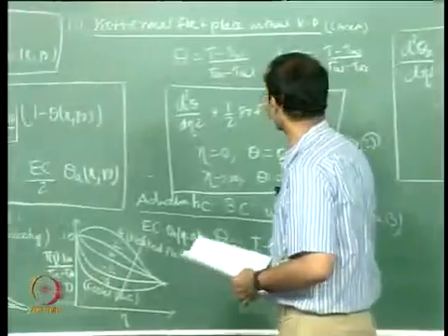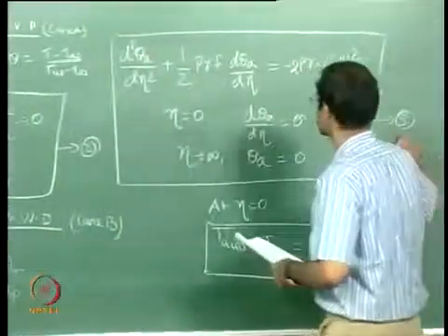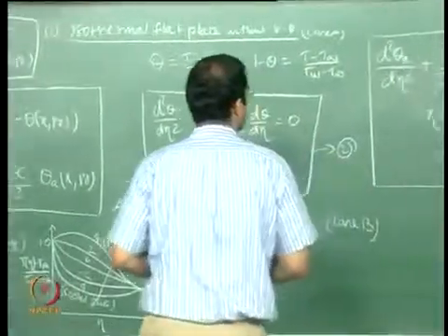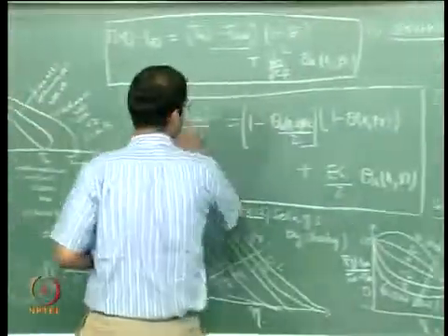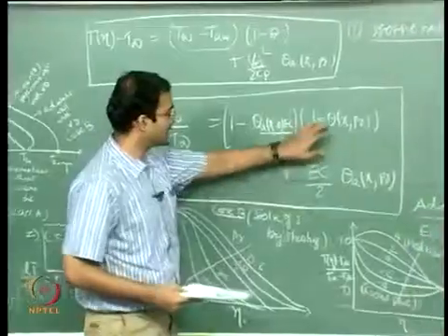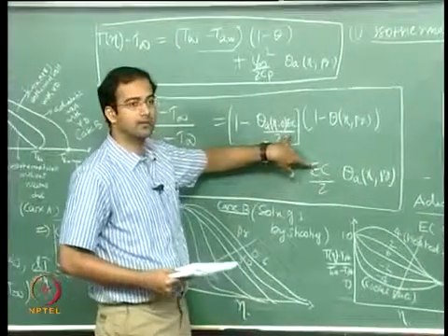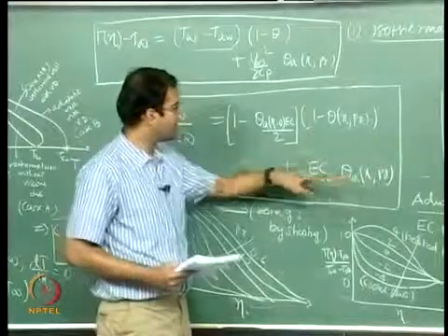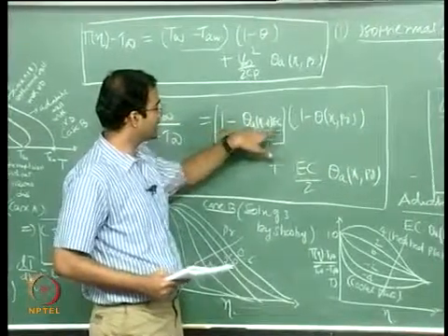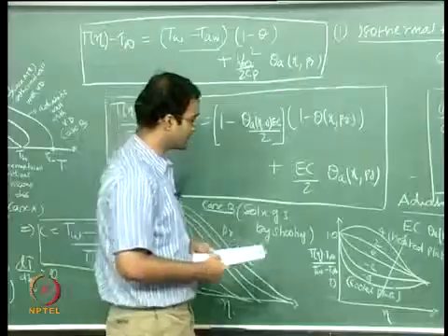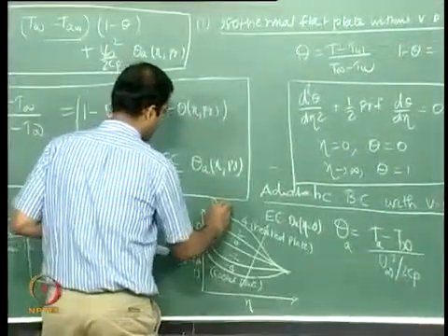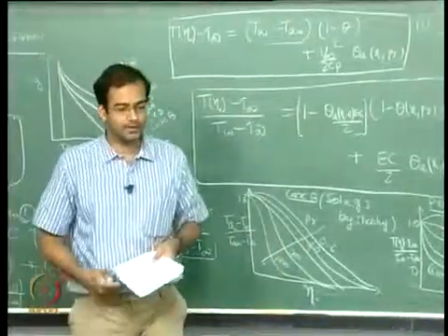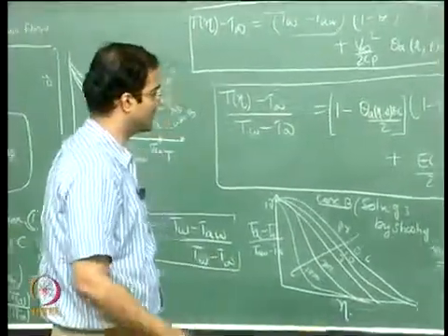So if you look at the solution for this problem 3, and if you look at the generic solution here, this depends on theta A and Eckert number. So you have to plot this for a particular value of Prandtl number, for a particular value of theta A at eta equal to 0 Eckert number. Okay, so this could be for say Prandtl number around 1. You have to fix the Prandtl number here, because there are too many parameters.